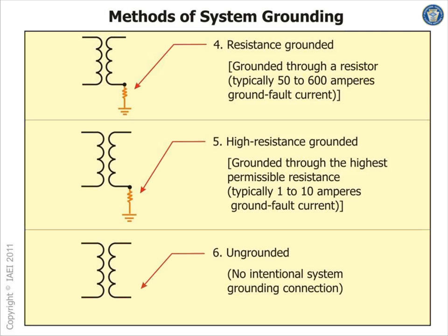Does that make sense? They use them a lot in high voltage systems. I did a couple of grounding classes, and they are also going into impedance grounding in low voltage systems, just because of the transient. Right, so this is the grounding at your main service transformer.